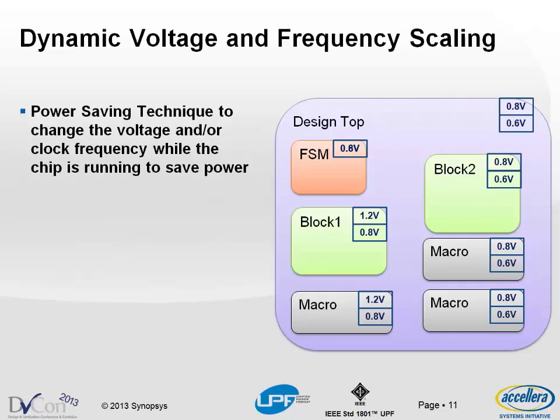So this is a power management technique where, on the fly, let's say I'm operating at a specific state, and you hit a particular state and say, well, instead of being at 0.8 volts, because someone tripped a video on their smartphone, I'm going to move up to 1.2 volts so I can actually operate faster and provide the performance.